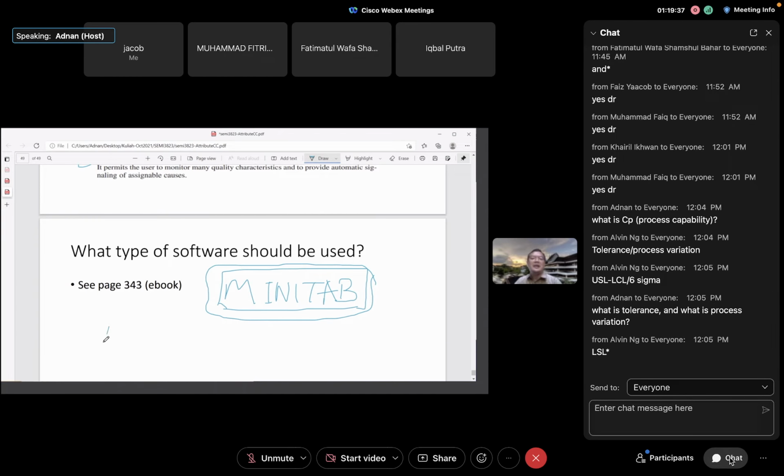There are different effects on the sensitivity of the control charting. Let's say this is 8 o'clock, 9 o'clock, and you want to collect the sample as it is being produced throughout this. Let's say you select one here, one here, one here, or you select an instant time period.